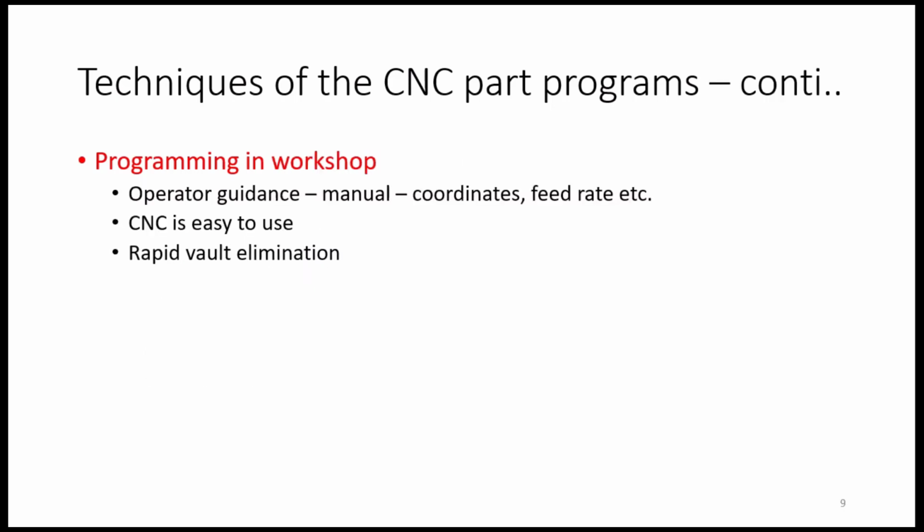Then the second technique is programming in the workshop. Whenever you write the program just sitting in a planning department, there might be some practical issues which you forgot to take into consideration while writing the program. That can be omitted when you are programming in the workshop. This can be useful by asking the operators who are working on the CNC machine. He can guide you well while writing the program.